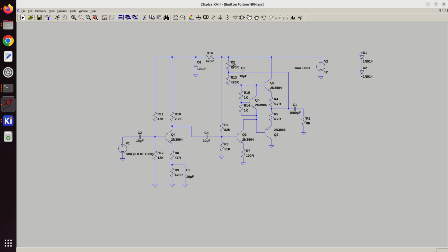If we put these up to possibly 10k or something, you wouldn't have enough current flowing. Let's say these have a beta of 100. Well, you need to be able to put in a milliamp in here if you want 100 milliamps to it. And 10k won't give you that. Actually, it'll be very close.